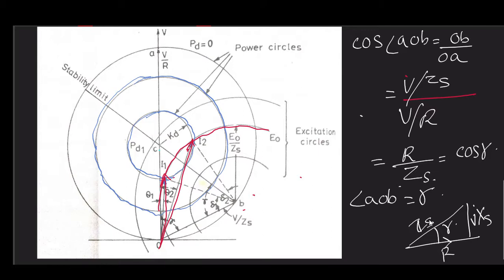If you are still in confusion, you can also utilize that sine wave curve, what I discussed in the last lecture, that for delta you are having two values of delta that give you the same power. Now the question is, which one should we use? One thing that is very clear from this picture is that we can have delta 1 for I1, and delta 2 for I2.